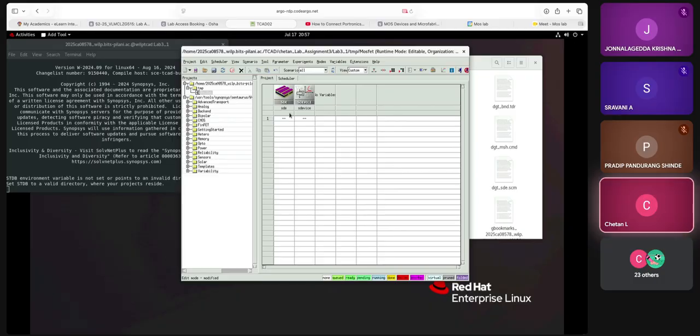Now remember, this is where our activity starts, editing the things here. We need to input the command. For SDE, we will copy our .scm file. For S device, we will copy the .cmd file. This is the basic thing. Just remember this. For SDE, we will copy the .scm file.